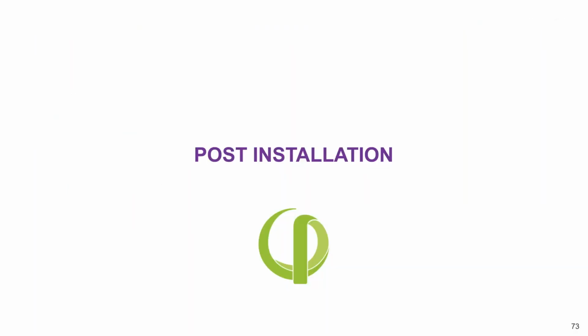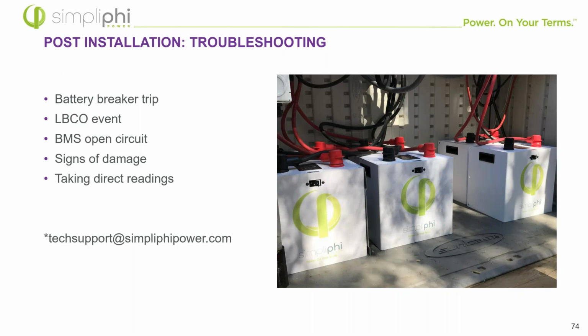Okay, post-installation. So this is the last little section I have for the Q&A. Real quick, we'll just go through this. As far as post-installation goes, checking health on the lithium battery is not that important. You can always check the voltages, make sure everything seems really even across the board. But other than that, just keep an eye out for things like battery breakers tripping, maybe the low battery cutouts happening too often when it shouldn't be. A battery management system open circuit, meaning these batteries are not showing voltage anymore, but the battery breaker is still in the on position, or any other signs of damage.